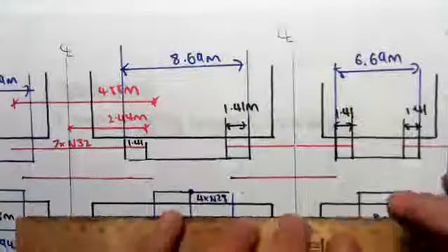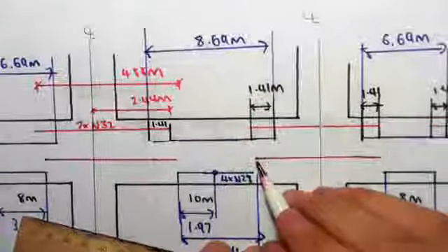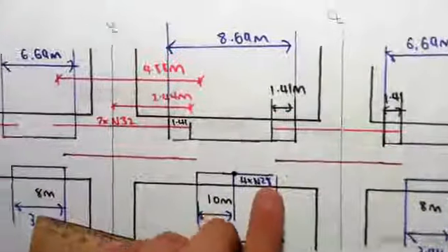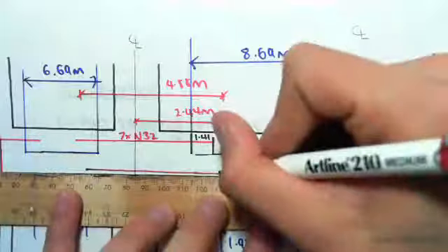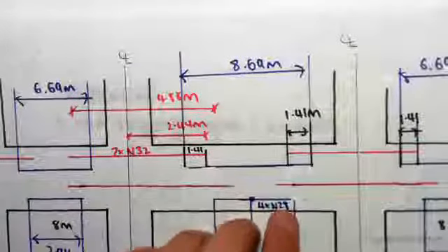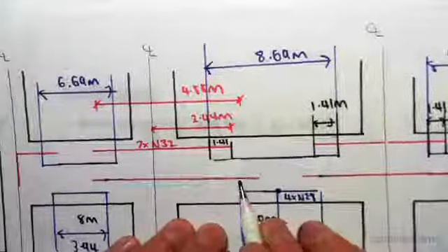To there. So you can see that from there to there matches, and from there to there matches, and from there to there, and there and there. Now that's going to be the length. We also need to extend it such that it laps. So we're lapping the bars. We need to extend it a bit further, and we now need to find this splice length. So the length from there to there, and the length from there to there.